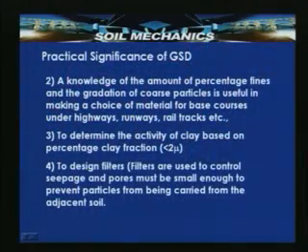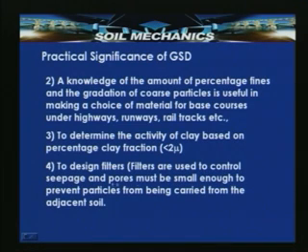And to design filters: a number of filters are required either to provide drainage in case of parking lots or road subbases, and in case of retaining walls, or along canal banks. So, filters are used to control seepage, and pores must be small enough to prevent the particles from being carried from the adjacent soil. That is the criterion for designing the filters.